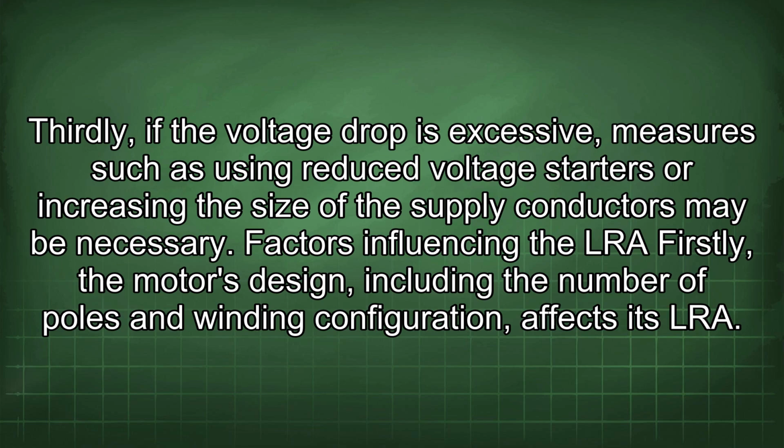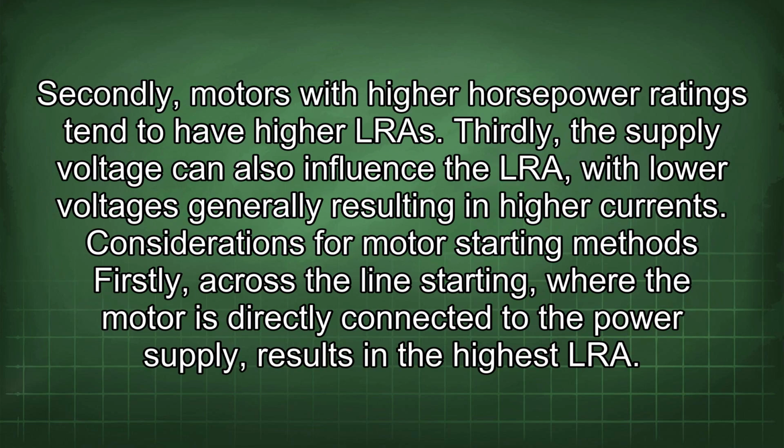Factors influencing the LRA: firstly, the motor's design, including the number of poles and winding configuration, affects its LRA. Secondly, motors with higher horsepower ratings tend to have higher LRA. Thirdly, the supply voltage can also influence the LRA, with lower voltages generally resulting in higher currents.